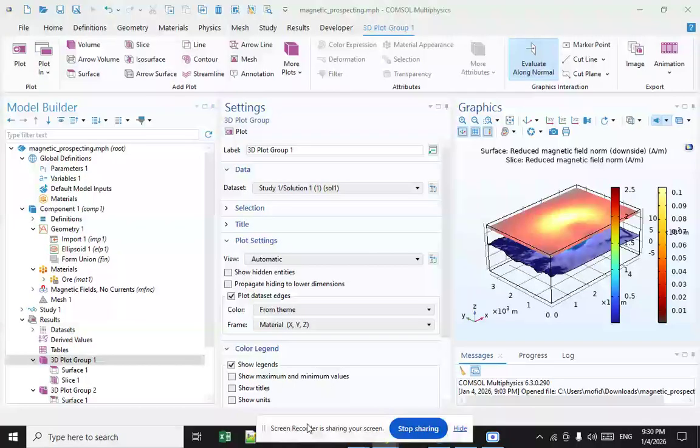The chief limitation of magnetometer survey is that the subtle features of interest may be obscured by highly magnetic geologic or modern materials. Magnetometry largely relies on the fact that the topsoil has a higher magnetic susceptibility than most bedrocks or subsoils. This is because of the concentration of iron minerals in the topsoils, often weathered from the bedrock.